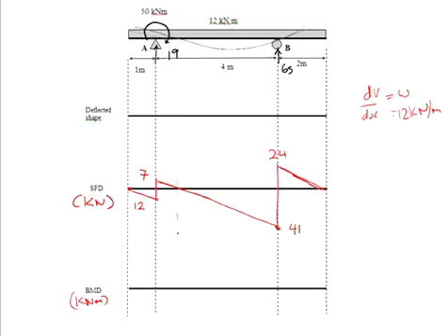How about everyone that got it wrong and everyone that didn't have paper B now? Pull out a piece of paper and attempt to draw the bending moment diagram. We have time. So remember, dM/dx is equal to V. So how about I give you 5 minutes? Find where your bending moment is 0. Note those points. And then on your diagram, go positive shear force, downward slope, negative shear force, upward slope. Do it now. Why not?